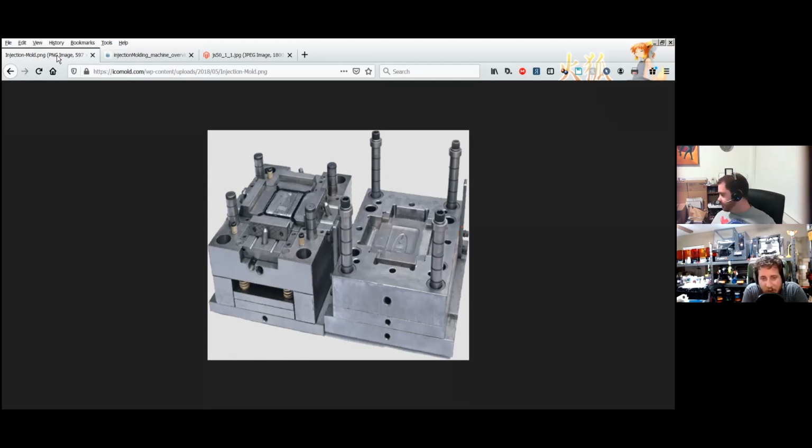Because of those micro cracks and fissures between layers, you can have issues with parts not being able to be sanitized. And that was really my big concern with these 3D printed masks, and actually why we never went into production of them. We tried them out. It's a great idea in theory. And the Montana Mask Company, the guys that put all the effort into this, use special filament that's got copper in it and other metals that sanitize naturally, like brass, bronze, copper. Those metal ions will disrupt the cell walls of bacteria and the capsules of viruses.